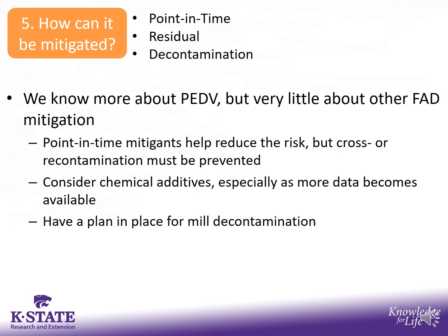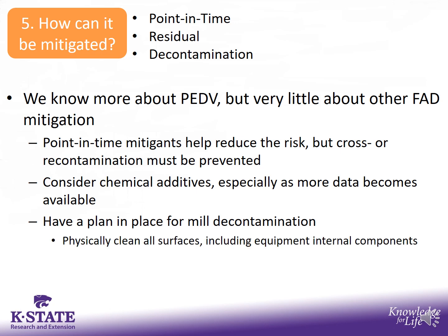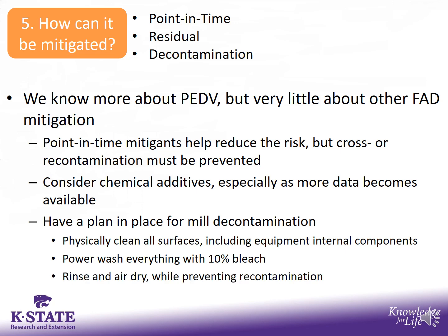We also really recommend that you have a plan in place for mill decontamination. It is not a fun process. Right now, what it involves is physically cleaning all surfaces, including equipment internal components, power washing everything with 10% bleach, and then rinsing and air drying while preventing recontamination. We hope that no facilities will have to go through this because that's an ugly process and feed mills were not designed to do that. And perhaps more than anything, that's why we highly recommend improving biosecurity to try to keep these viruses out of the feed mill.